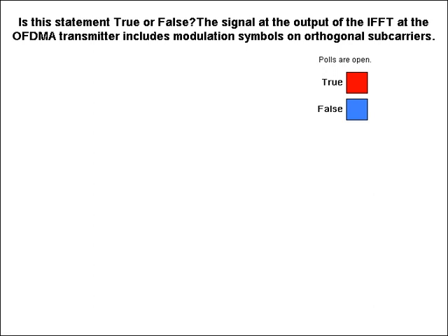Okay, we have a question. For each IFFT input pair, yes, it's amplitude and phase, correct. It's a modulation symbol, so there will be an amplitude and phase. It will be a complex number at the input of IFFT, that is correct. Because if you are using 16QAM or 64QAM, you have amplitude and phase associated with that modulation symbol. So you are right. Amplitude and angle, both correct.